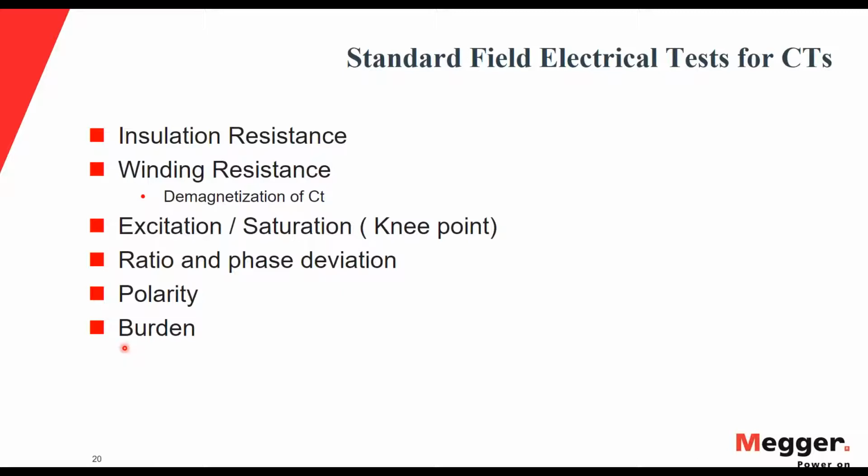And it should not exceed the specified burden of the CT. Otherwise, your CT will not work as per specified.